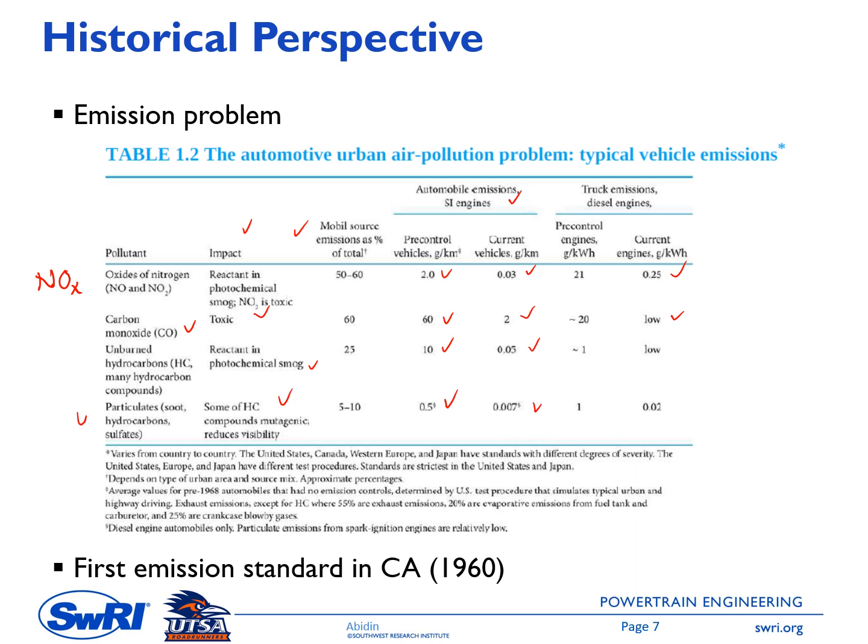Because of lower fuel or higher air amount, we have much lower CO in the diesel engine. It also has lower unburned hydrocarbon compared to the spark ignited engine. And particulate or soot is a typical emission from a diesel engine, so it has much higher soot compared to the spark ignited engine.